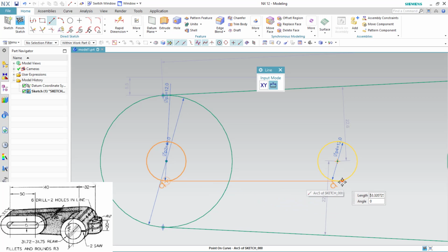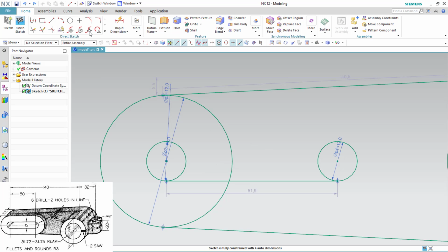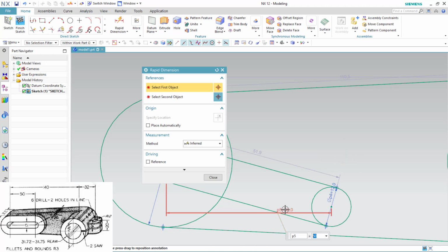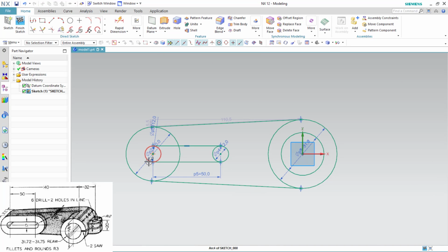Referring the edge is quite difficult, so you can use the tangents instead of that. Okay, control side, and we can redraw the same thing. Yeah, you can now use the quick trim and delete. Before that, you can assign the dimension. It is 50, right? Yep. So you can make that line horizontal, shortcut one, instead of selecting the point and making it horizontal, right? Yeah.